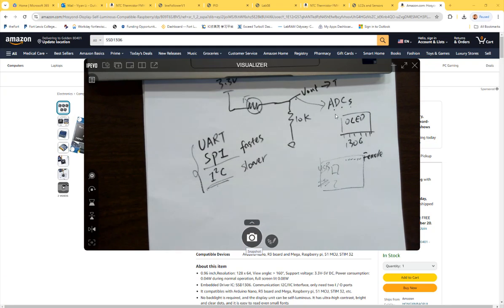Why is that? With longer lines, you can come up with impedance issues, where it takes longer for a line to rise high. Yeah, impedance and parasitic capacitance, right? Because all these cables are wrapped with what? The rubber, whatever materials. So there are capacitors everywhere, even though they are not physical capacitors. It's called parasitic capacitance. So basically the digital communication is charging and discharging those caps.